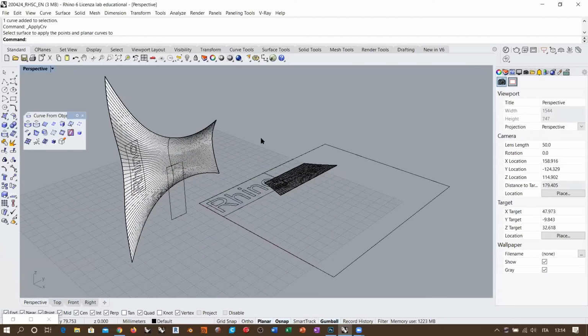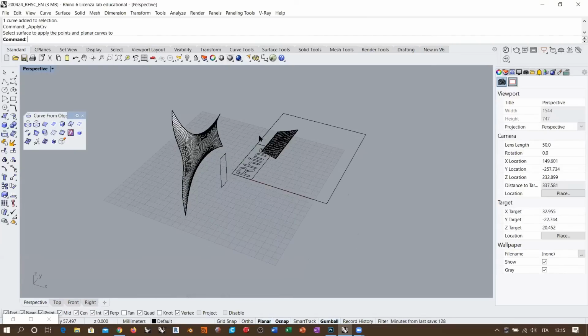If I understand well, when we speak about topological deformation, it's a parametrical consideration. Yeah. Actually, this is a different meaning of parametric. In Grasshopper, parametric means that you work with parameters that affect the final result. But in this case, we are referring to the parametric representation of the surface, which is for the curves the famous T parameter, which represents time. But as a surface is a two-dimensional domain, you have U and V. And eventually W that determines the direction of the positive normal.